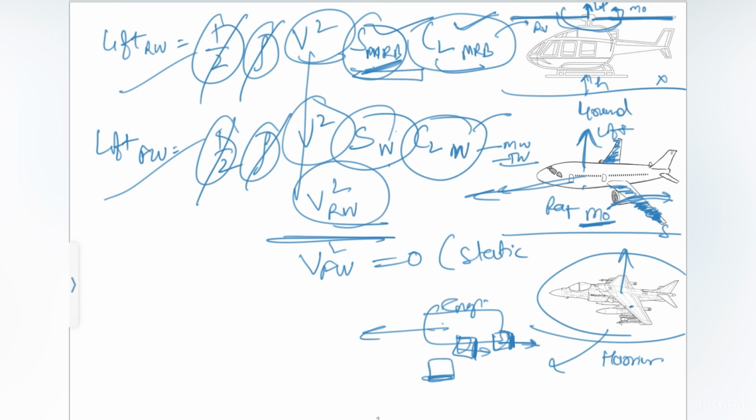But in case the jet is positioned 90 degrees clockwise and gives a thrust down, then with Newton's third law, the aircraft goes up. You can see this is the nozzle, this is the air intake, and there is the engine, and that's how this Harrier can take off and land. There's a special term, VTOL, vertical takeoff and landing, which is a speciality of this kind of aircraft.